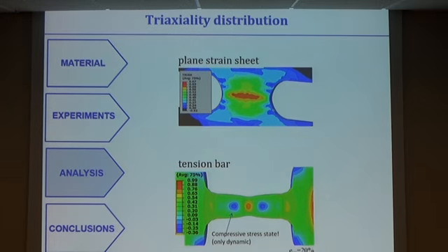And then to come to a more in-depth understanding and an analysis of the results I just presented, we also carried out some very basic finite element simulations. To model the plasticity, we used the Johnson-Cook hardening model to take into account thermal softening and strain rate hardening, and we combined that model with the Johnson-Cook phenomenological fracture model. And actually, much to our surprise, we obtained very beautiful results, as I will show. So why did we do the modeling work? We wanted to see what we got in the material during the fracture process.